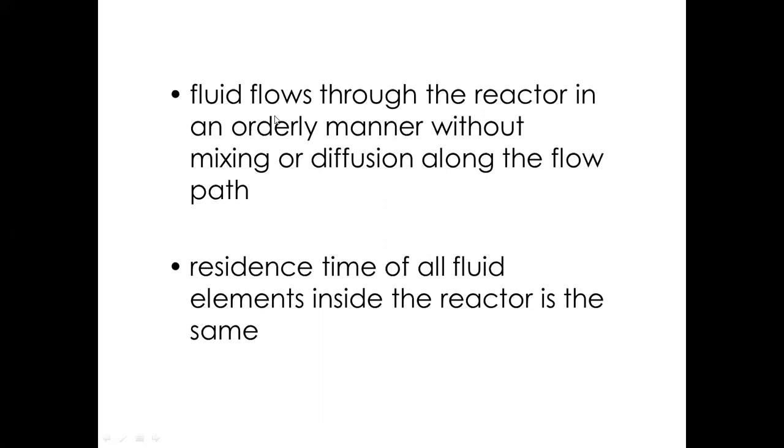Now, speaking of fluid elements, if we cut a disc along your cylindrical plug flow reactor, it's comparable to a volume element. These volume elements have the same residence time inside the plug flow reactor, so each elemental volume has remained inside your reactor for the same amount of time.